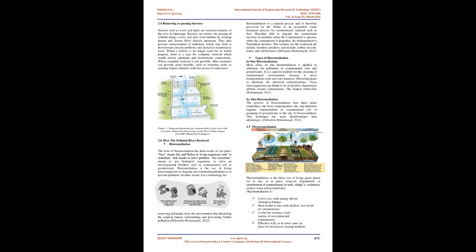In-stream enhancement. If floodplains have been reclaimed and developed, which is the case in most urban areas, it is often not feasible to make space for large-scale river restoration. If the river has concrete banks or bed, which is again often the case in urban areas, reinstating some natural processes within the river channel can be the next best option.